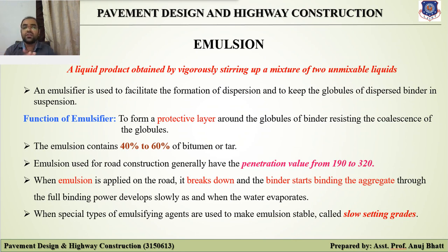The fourth is that the work progress is very fast, and obviously the time required for heating bituminous material can be saved. The fifth and last advantage, we can say, is that emulsion can be used in all weather. Even during the rains, we can use the emulsion for resurfacing or to construct a proper binder surface. During the rainy season too, we can use emulsion in the bituminous mix.